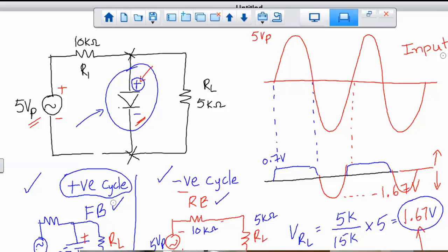Positive cycle, is it open? It's all the same signal coming through. It's just when it goes across that axis, it's now acting as a reverse bias. See, the positive cycle always makes that diode what? So what is the voltage on the diode? Wherever you see positive cycle, that would be 0.7 and that's it.